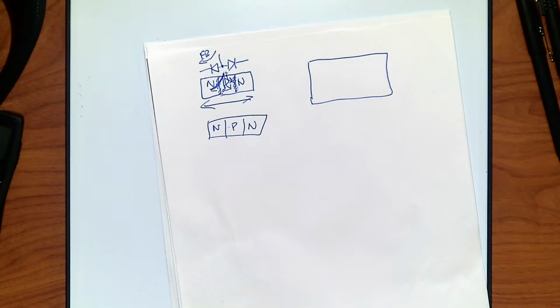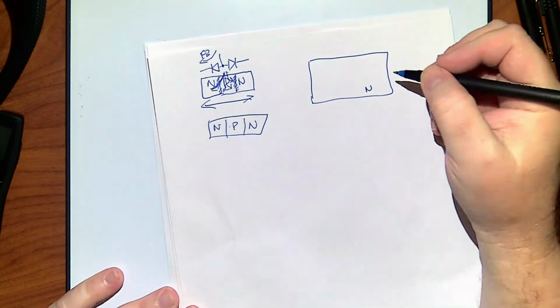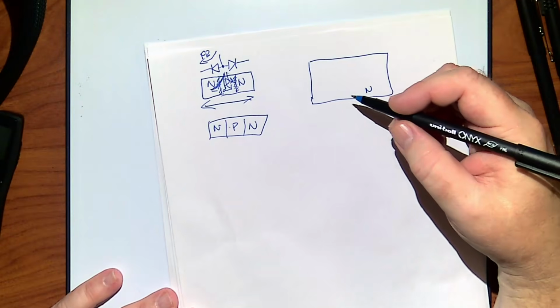So whatever the background dopant value you want for this, you'll often do it as whatever that is. Let's say, for instance, I make the background N type. At that point I would just get a silicon wafer, which is you pull that cylinder out and then you slice it. Now you have a wafer of this, and I could make it N-type, pretty nice and even. And then let's say I wanted to diffuse P-type into this.